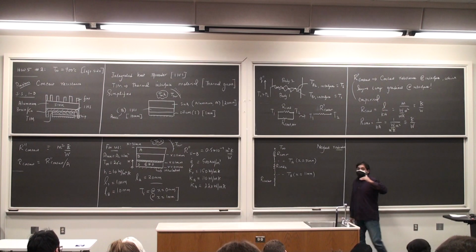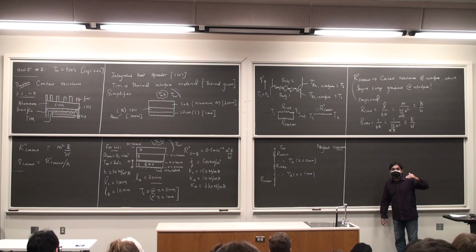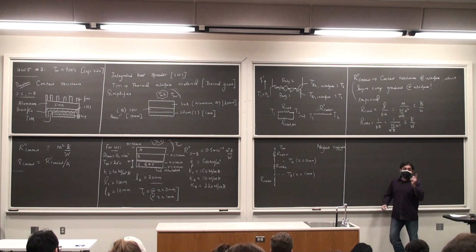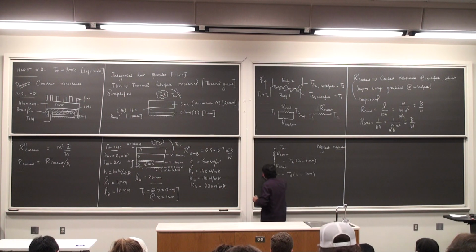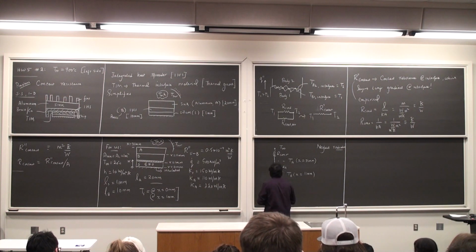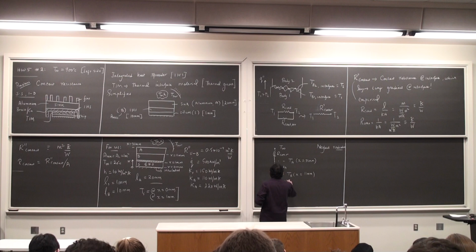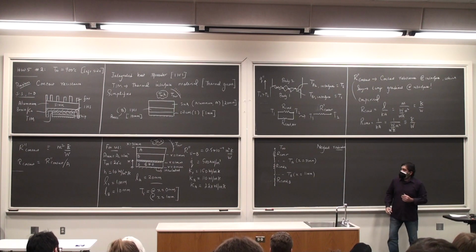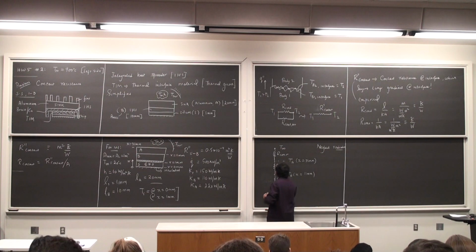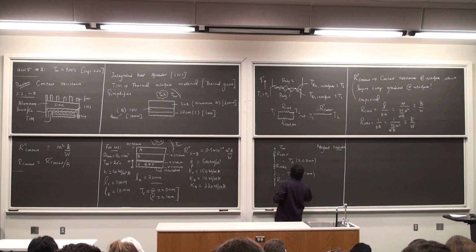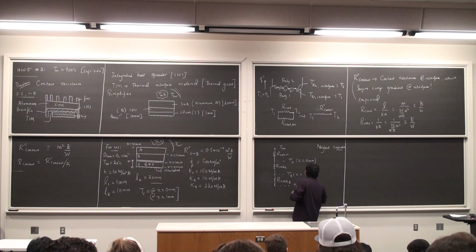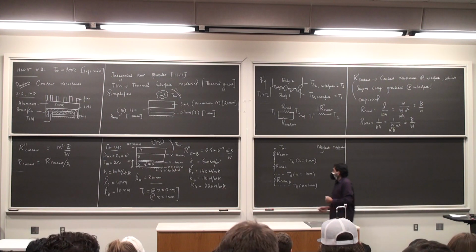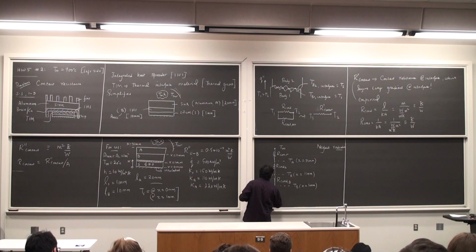Which means that when I'm writing the temperature at the next node, it should be the temperature of the silicon body at x equals, I'm sorry, I forgot the conduction through the brass, absolutely sorry about that. This is conduction here through the brass body, through the thickness of that. And then I reach temperature TB at x equals 1 millimeter, and then I have the contact resistance coming in between the silicon top layer and the heat spreader.